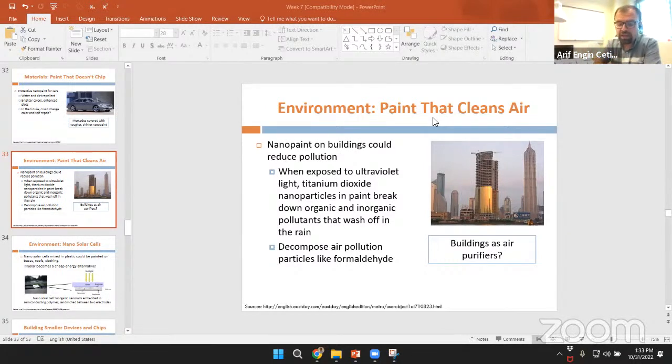But what I can tell you is nanomaterial definitely helps you to increase the signal of your biosensing technology. So for example, you are developing a DNA biosensor using an electrochemical device. If you tag the probe or DNA sample with a nanomaterial or a nanoparticle, it allows you to increase the signal coming from your electrodes.